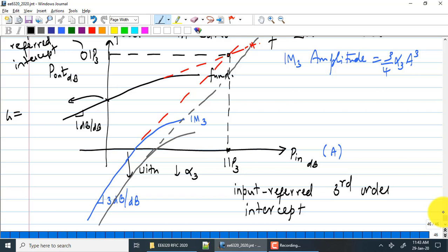With the second order, calculate the nonlinear term. Now that nonlinearity can be modeled as a polynomial nonlinearity for any amplifier. If you have done a good job, it will be weakly nonlinear, so that alpha 3 will be very small. If you change the bias currents, voltages and power supply, you will change alpha 3 for sure.